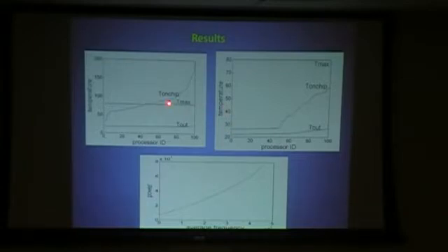For example, just about half of the chips in about 100 servers in our simulation environment violate the maximum temperature constraint, even though the air surrounding that server was within its manufacturer's specified constraint. So you can crank up your air conditioning, you can maintain the temperature at 35, but still it doesn't do what you want it to do.